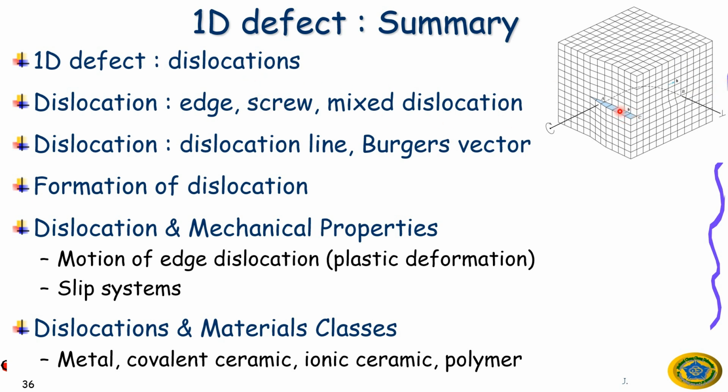And this is what we call screw dislocation. The second one is screw dislocation. The lattice on the top layer and bottom layer split, so it looks like a screw from the top to the bottom, like it's screwing, right? Do you know what a screwdriver is? Screwdriver, 螺丝起子. So screw like this. The mixed dislocation is the combination of the edge dislocation and screw dislocation.